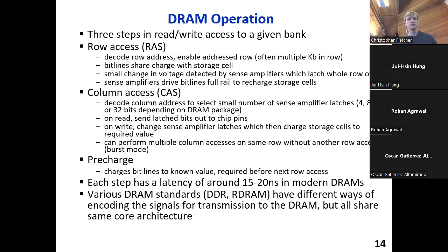Very good. Okay. So we have row address strobe, we have column address strobe. Finally, we have this thing called precharge. This is yet another thing baked into DRAM's design, which favors density over speed. We won't see how you can do better than this until we briefly talk about SRAM cells. SRAMs do not need this operation, even though they do it for optimization purposes, but it's fundamental in the case of DRAM. But we'll just explain what it is now.